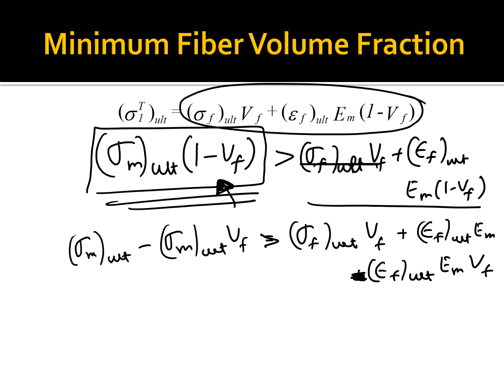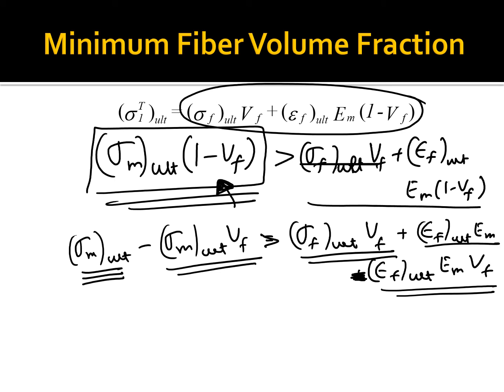If we bring these volume fraction terms together, take this to the right-hand side and keep this on the left-hand side, we'll find the value of Vf min, the minimum volume fraction needed so that the matrix can continue to take the load.